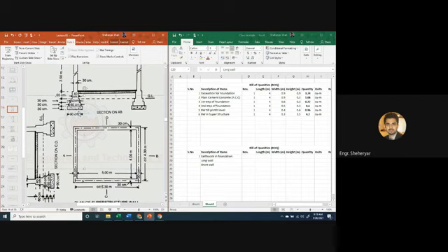So considering the 90 centimeter width, what will be the length of long walls and length of short walls? First decide which is your long wall and which is your short wall. Let's take the vertical walls as long walls and the horizontal walls as short walls. Now let's see the lengths of the long walls and short walls. What will be the length of long wall? 4.3 meter is the center to center distance, and 0.9 meters is the width of the wall.